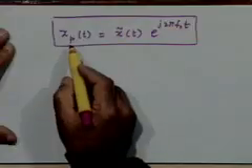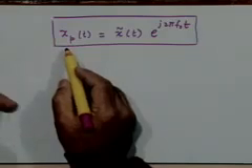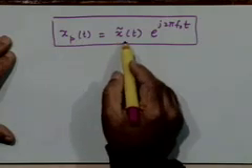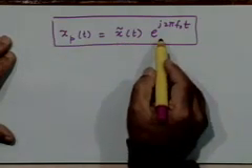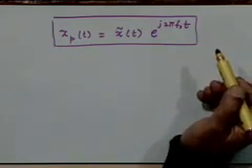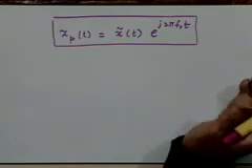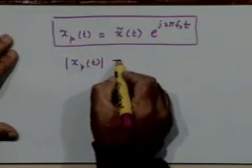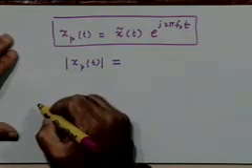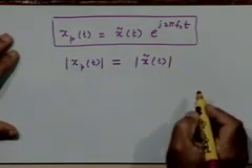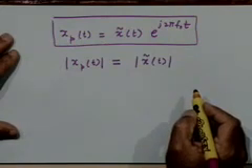What you have got is that the analytic version of the bandpass signal which was of interest to us can be expressed as the product of a complex valued low pass signal and e to the power j2 pi f naught t, a complex exponential, right? Fine. Any questions on this? Also, it's clear that the envelope of this signal would be equal to what? The modulus of this signal, right?